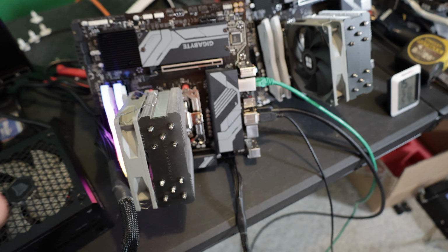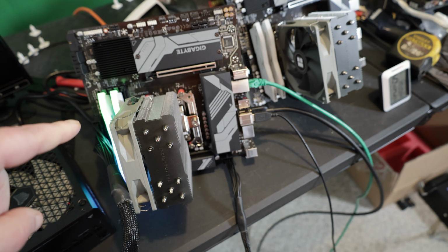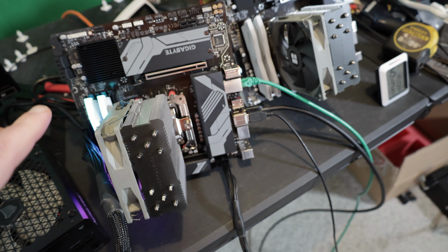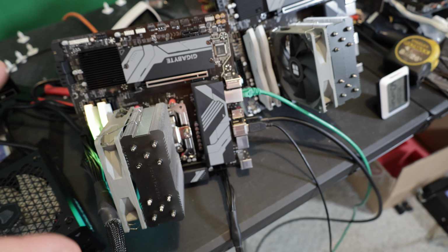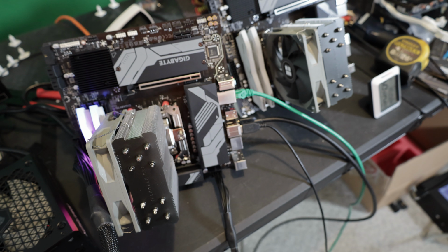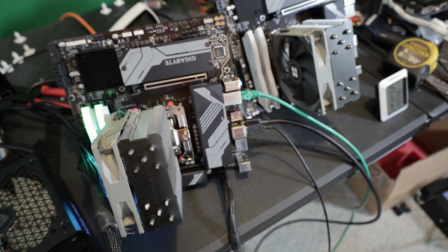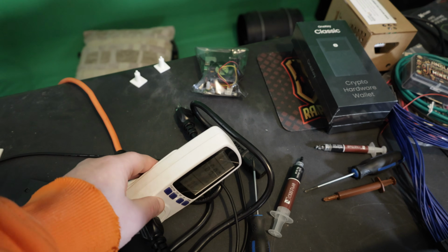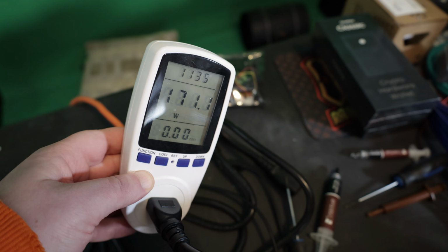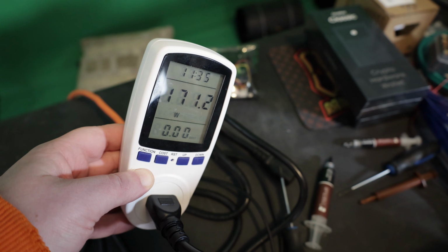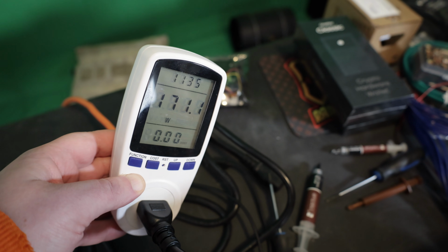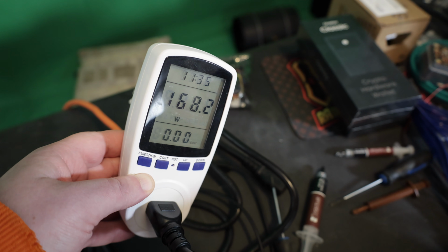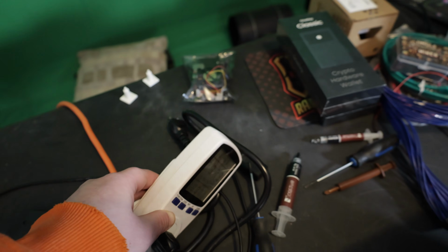All right, so I shut off PBO. I put it back to the 9.5 gigahertz and I dropped the voltage to 0.93. So I'm going to let it sit here. I'm probably done testing this one for now, see if it's stable. And then I'll decide if I want to drop the voltages some more or not. But let's just take a quick look at the power here based on 0.93 volts, and we are down to about, it's bouncing between 168 to 171 watts. So we are about 5 or 6 watts less than that 177 there, as we can see. So now that's all complete.